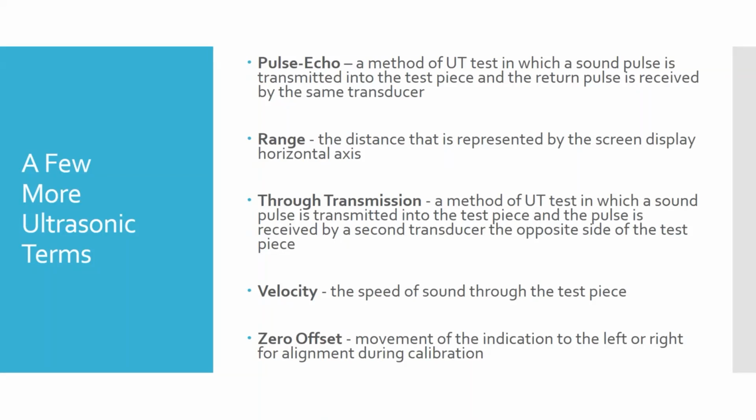This ultrasound can do fairly thick materials. It can do materials that are several feet, or when you start doing, remember we talked about surface wave or shear wave type setups? You can do pipelines that run underground. They have one little exposed area, and they can do a test that goes a mile down a pipeline and back, where it runs through the ground to look for cracks in a pipe. So that's pulse echo.